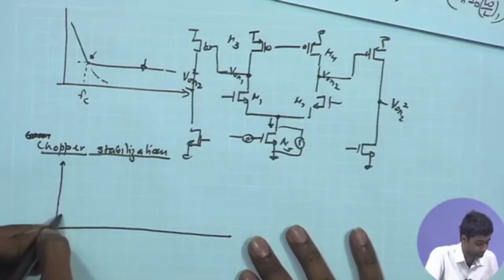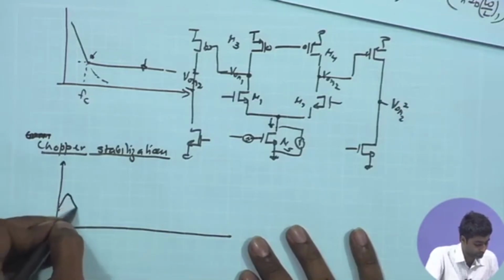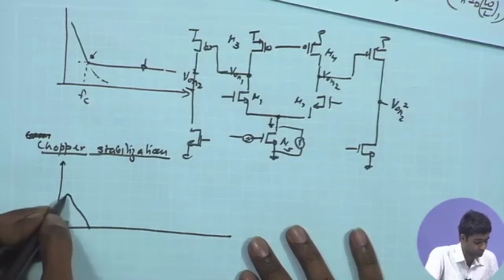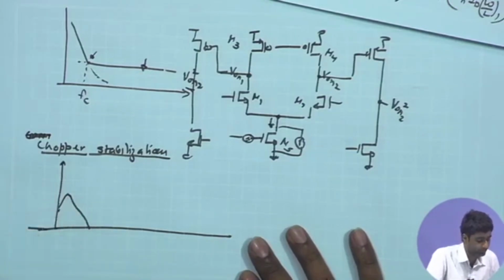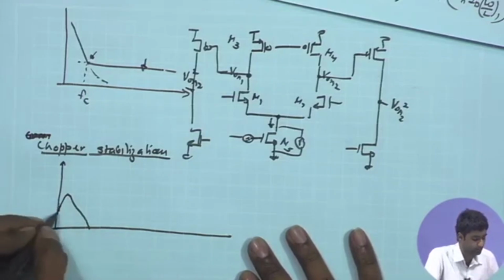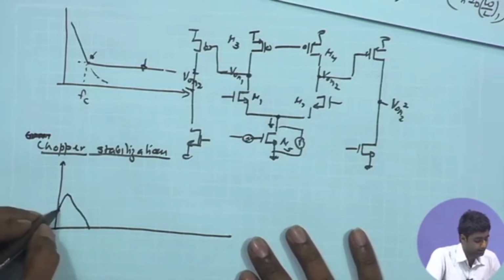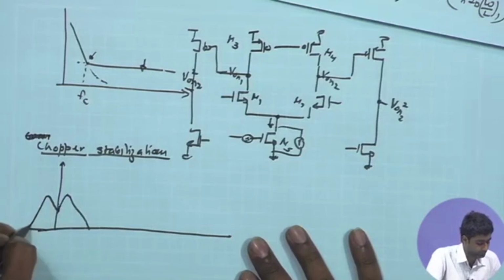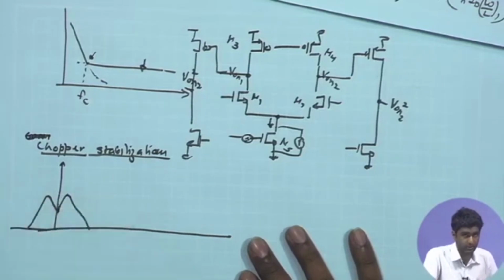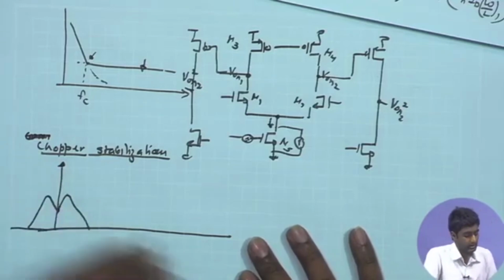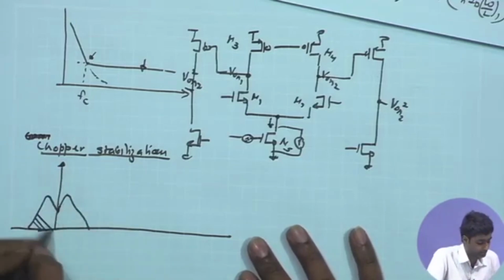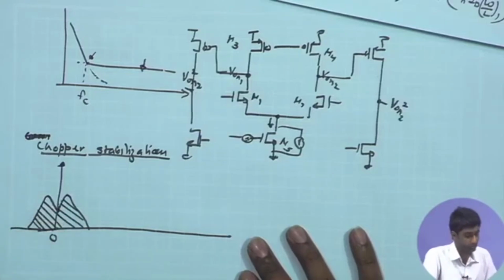For example, in our case, as we have said, the content of the signal may be peaking at close to a few tens of hertz, and it can have content going all the way down to 0.5 hertz. So, it can have some content very close to DC also. Therefore, if I look at the complex frequency spectrum, it will look like this. You have the positive and the negative frequency components in the complex frequency domain, and this is the overall signal spectrum centered around omega equal to 0.